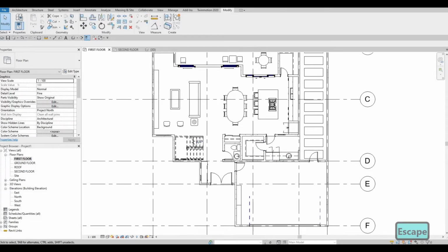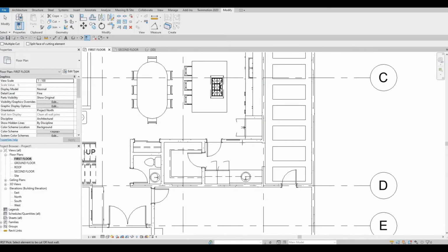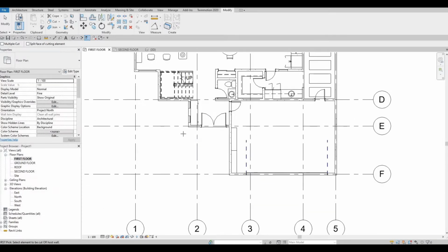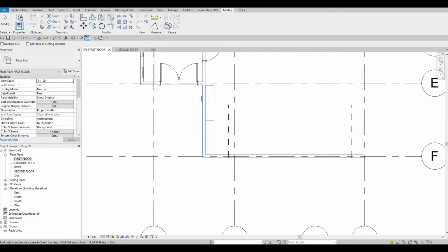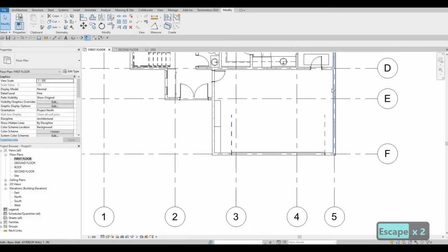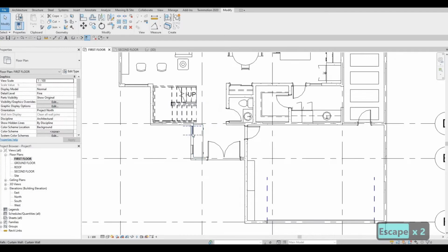We need to go to modify and cut geometry. And just remember where we added those. And that looks good. Sometimes I add one right here at the top of the wall. But it's up to you because this one is all the way to 2800, or right here just to have some light. So yeah, we could do this one right here.